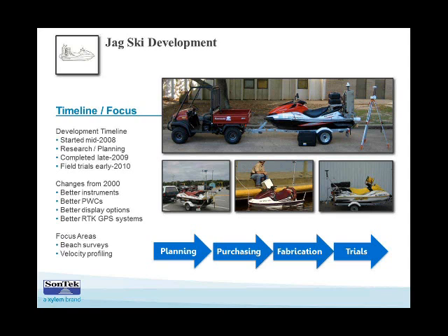You'll see some of our profiling that we did across one of the rivers, and this was going across the Appalachian River, and this is just a direct screenshot out of the River Surveyor Live software. And this top panel shows bathymetry, so there's a deep channel here on the left side of the transect, and it comes up to a marsh flat on the right. And then basically our vessel track and velocity profiles in the middle panel, and then the typical velocity plot that you see of depth and range across the transect.